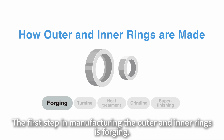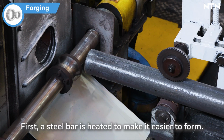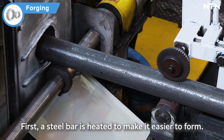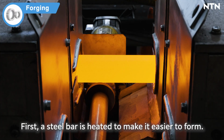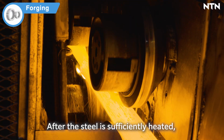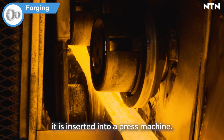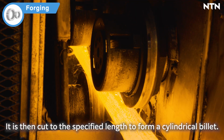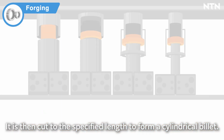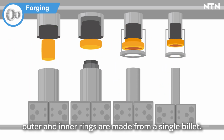The first step in manufacturing the outer and inner rings is forging. First, a steel bar is heated to make it easier to form. After the steel is sufficiently heated, it is inserted into a press machine. It is then cut to the specified length to form a cylindrical billet. Inside the press machine, outer and inner rings are made from a single billet.